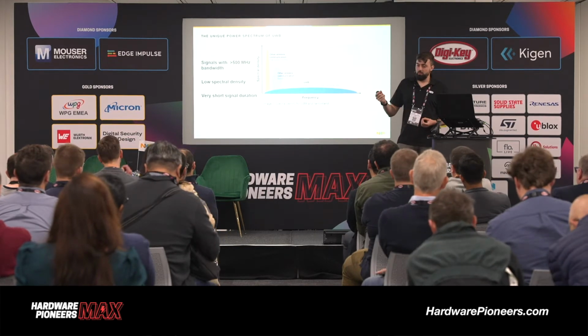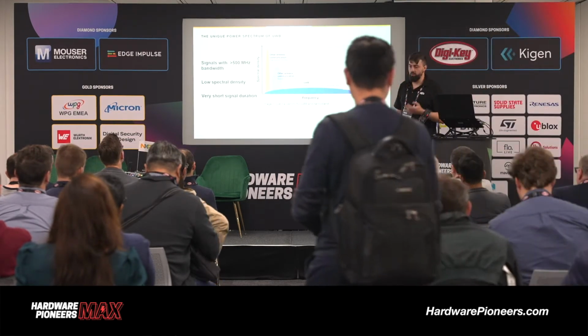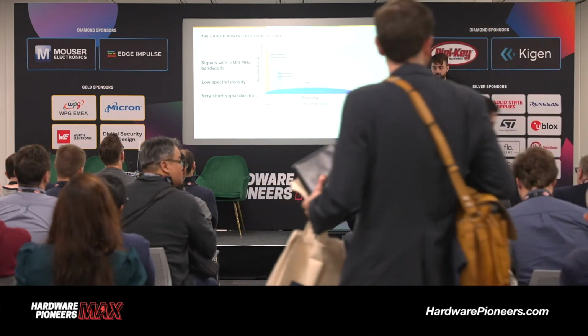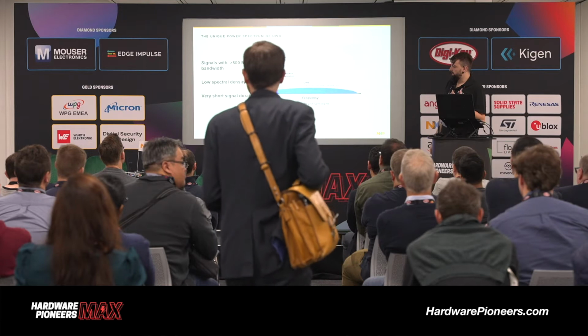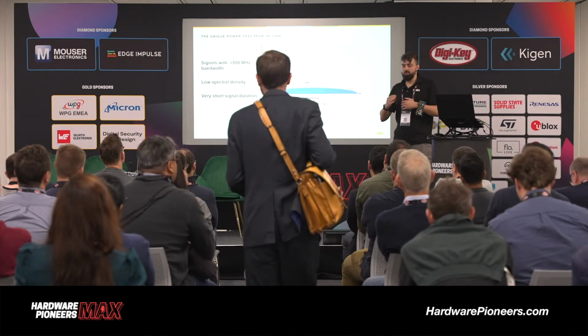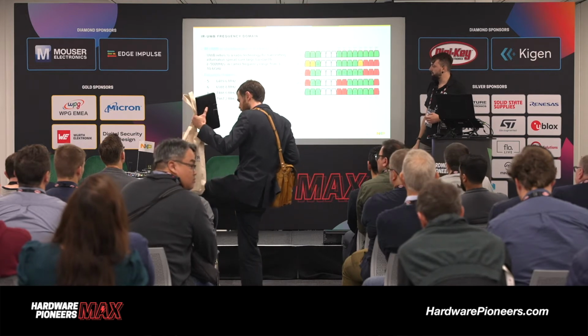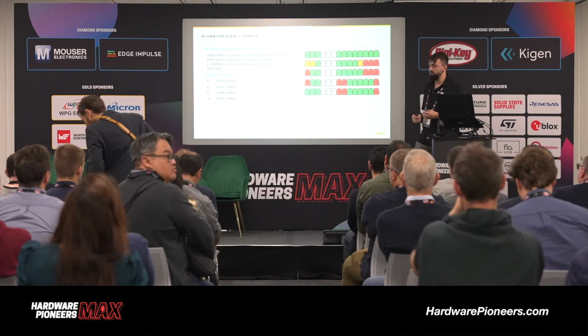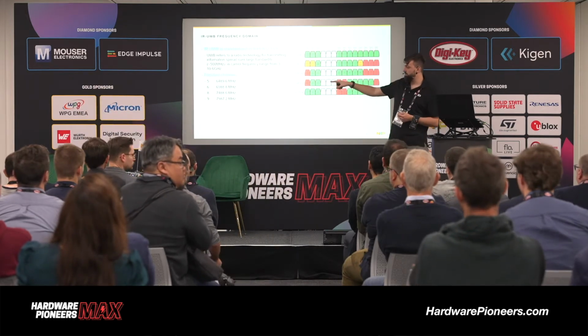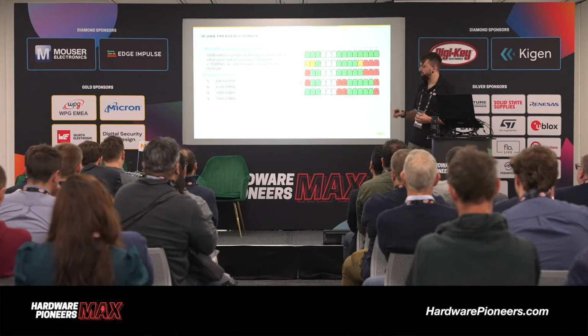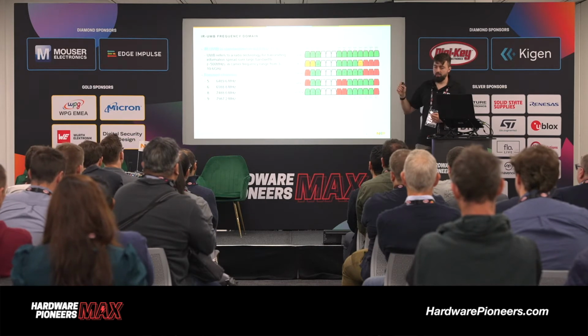It also means that we can use a very short signal duration, so that the signal doesn't interfere in the time frame that much. Right now, the most important channels we have are channels 5, 6, and 8, which cover the spectrum from 6.4 to 8 gigahertz.